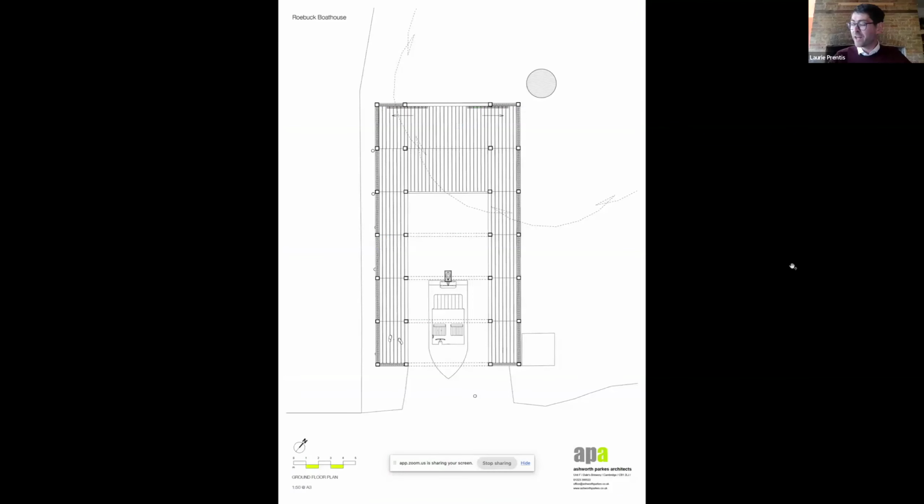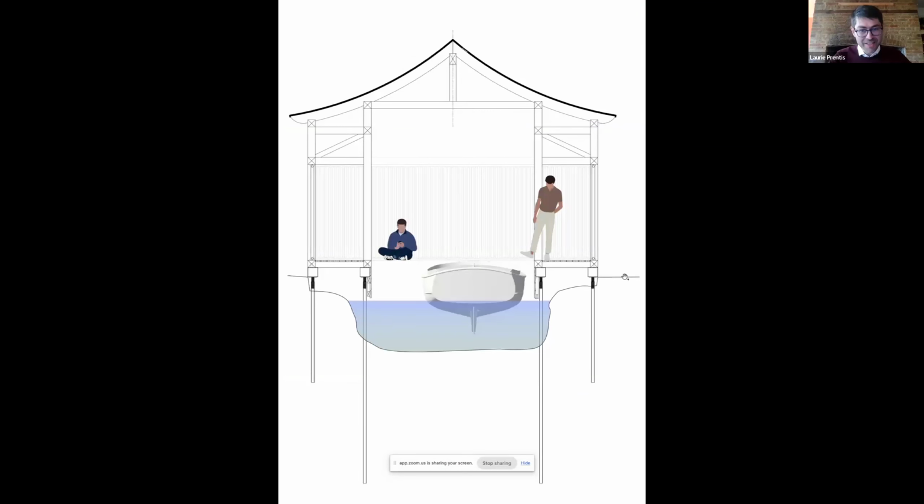And on top of the scaffold poles, there is a spreader plate. The spreader plate, I've got one here, I don't know if you can see on here, has a screw on it. So we turn this upside down, we put this on top of where we are, because eventually this building is probably going to move. And as it does, this gives us the facility to be able to adjust it as it goes along.